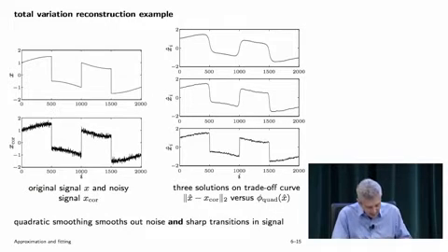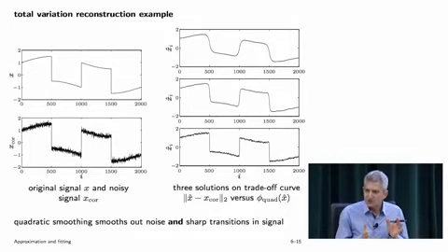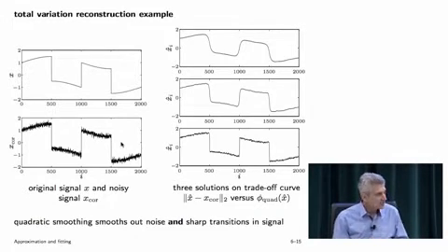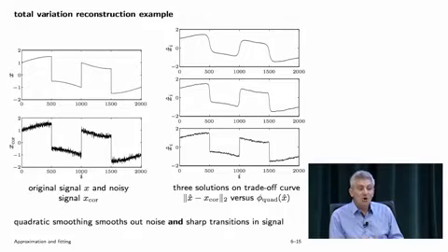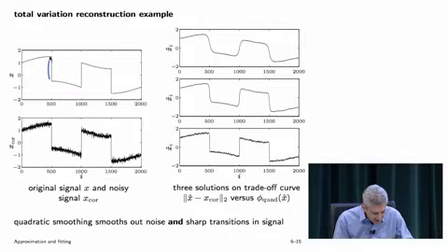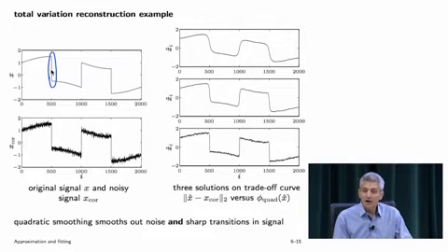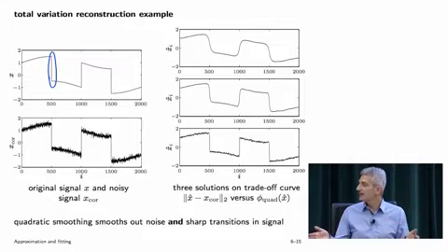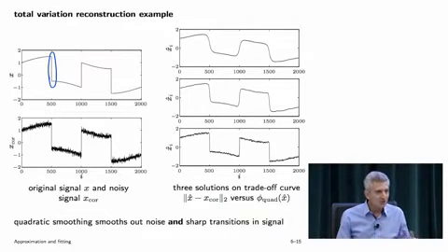So here's a picture. Here's the original signal. Right? It's got a smooth component, but these kind of jumps every so often. I mean, this is all just made up, right? So this is just to illustrate what happens. So here you have this signal, and then we add this high frequency noise to it, like that. So that's the corrupted signal, right? Now, one of the problems here is that you don't have this frequency scale separation, because the original signal has these jumps, and a jump, if you know about Fourier analysis and all that kind of stuff, roughly, is going to contain a lot of high frequency. So you don't have the spectral separation of the underlying signal and the noise here.